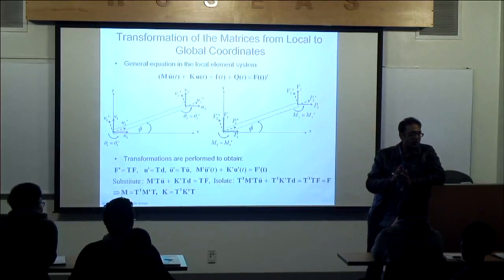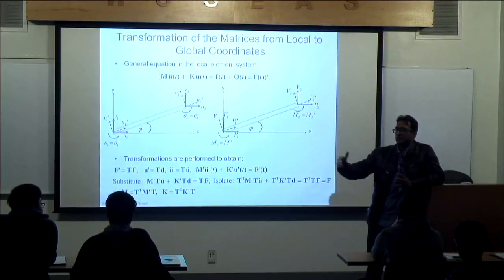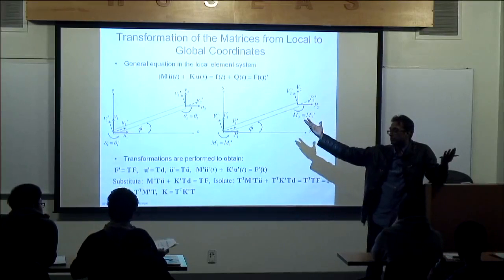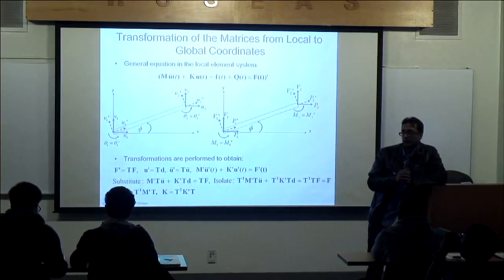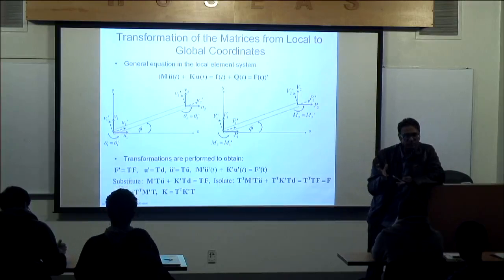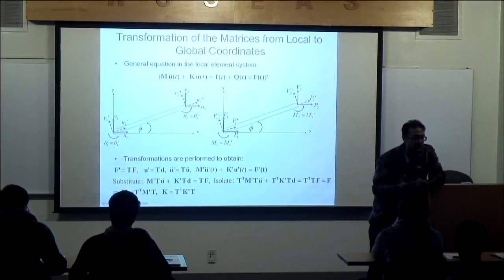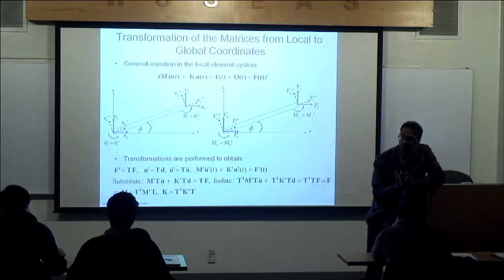So we know that not all those modes are relevant. And so if I can describe the dynamic response of the system in terms of, let's say, 10 modes, and it's basically a linear combination of these 10 modes, then I only have 10 degrees of freedom to describe a 1,000,000 degree of freedom structure. And I can get the stresses and the strains and the displacements for a problem that has been reduced in size from 1,000,000 degrees of freedom to maybe 10 degrees of freedom. And maybe I'll get very similar responses. This only, of course, works for linear systems.